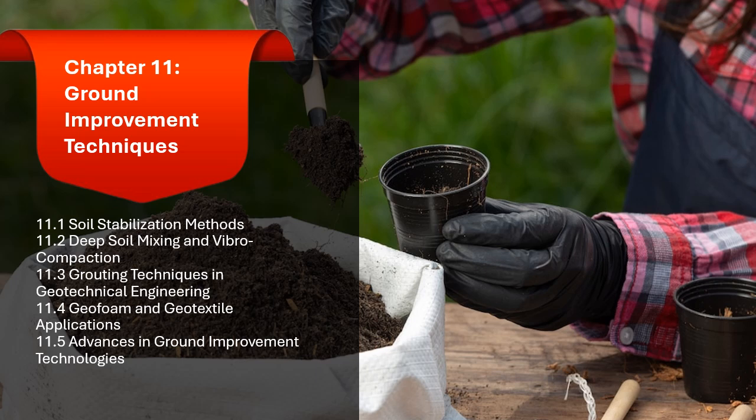As the vibraflot vibrates, the soil particles are rearranged and compacted. The process effectively reduces the void ratio between the particles and increases the density of the soil. 3. Soil improvement.